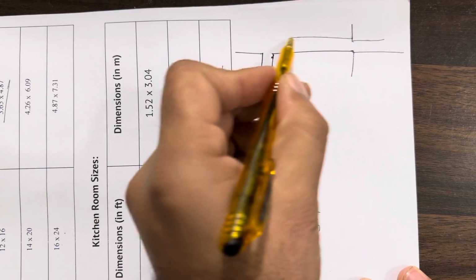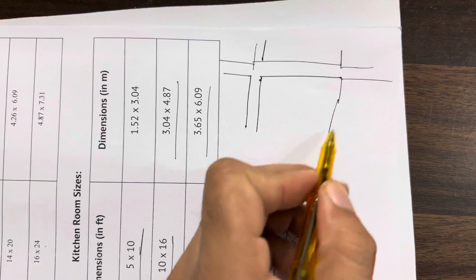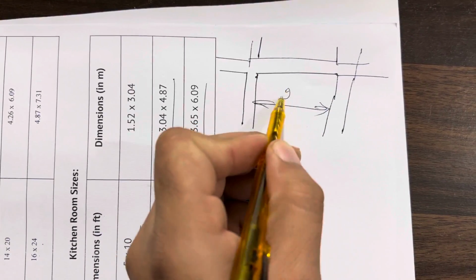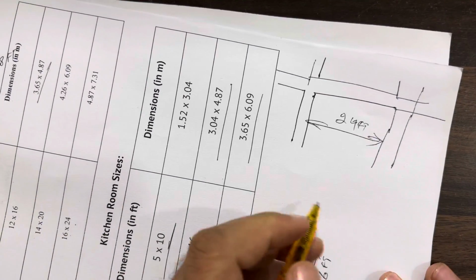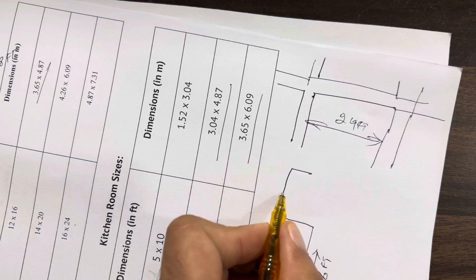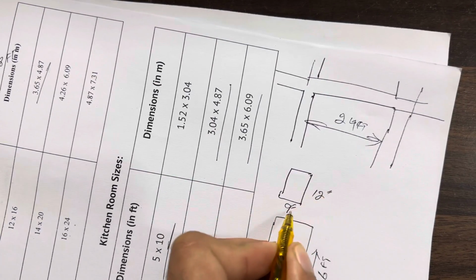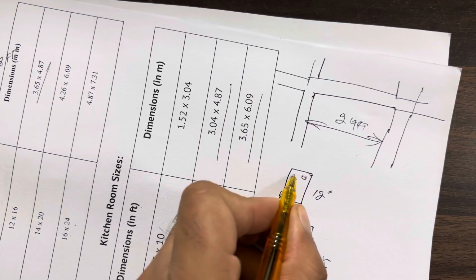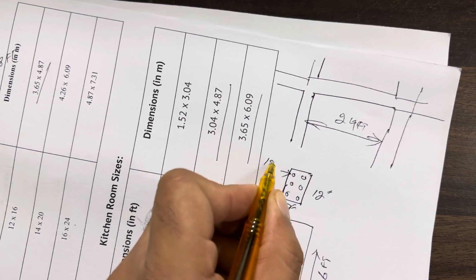So this is the span which is 24 feet. For 24 feet span, don't use less than the column size 9 inches by 12 inches. This is the minimum size of RCC column, and use 6 steel rods, and the dia should not be less than 12 millimeter.